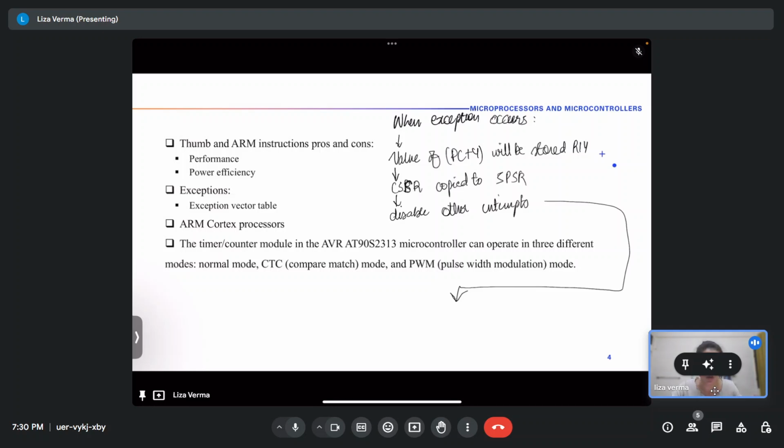If it is from FIQ, you don't want any other high priority interrupt, because this one came first. You want to execute the instructions in the ISR of this interrupt first. No other FIQ should be allowed, so you disable FIQs also.